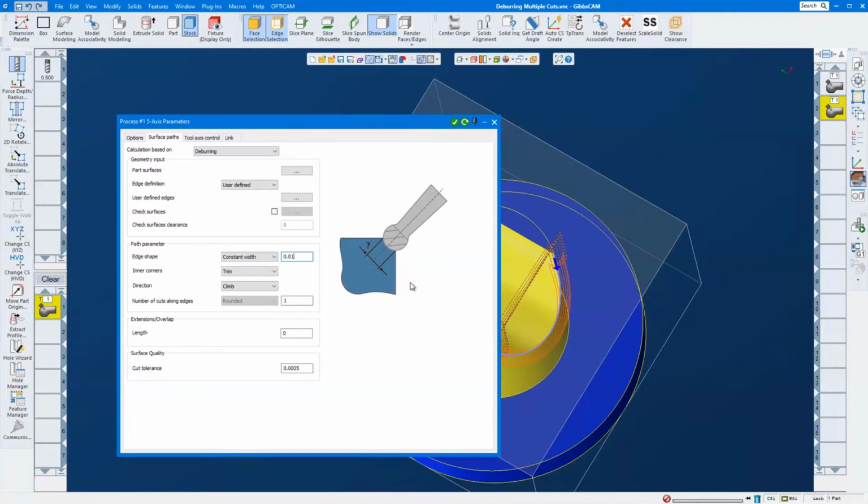Yeah, just being able to tilt the tool would be nice, if you could just give it a 5-degree tilt sometimes, because there've been places where I shank out. And the only way I could do it is to create a tool with a 10 thou shank and a 50 or 60 thou ball, which is unreasonable. But if I could tilt the tool, or tell it I want to be 20 thou off center, above center, or below center. I'll send that in, and it may be something they're already working on.